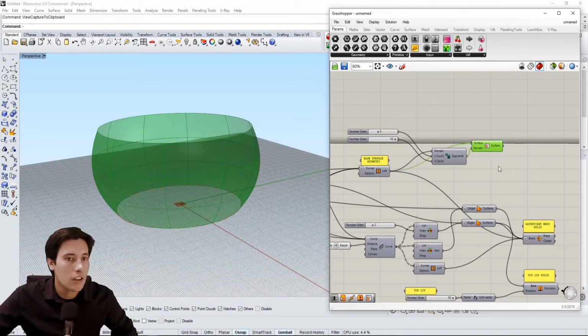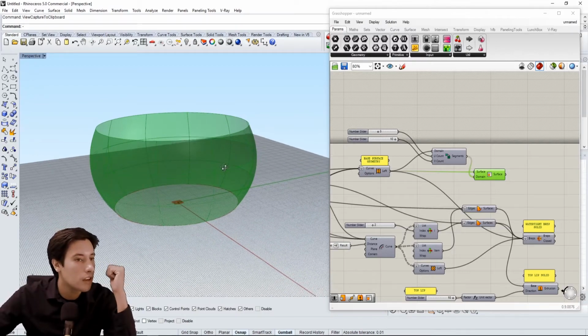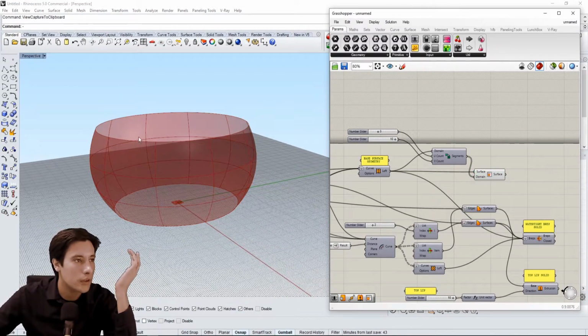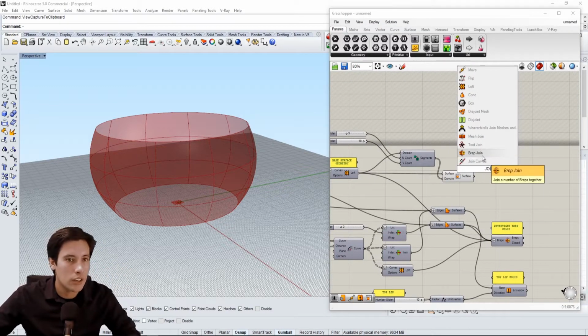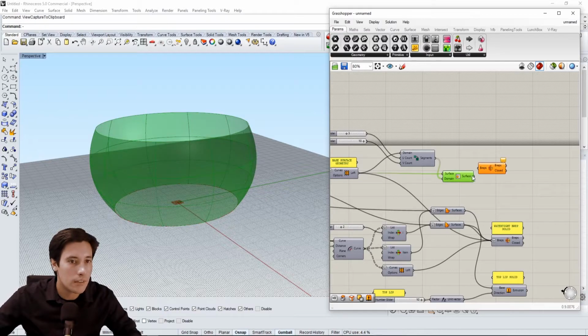And with this geometry we can do so many things. The first one I'm going to do is show you how to extract some pipes out of this and then use that for the geometry. So let's join together all of these subdivides into one solid, so I'll flatten it also, into one open B-rep that has all of these edges still contained inside of it.